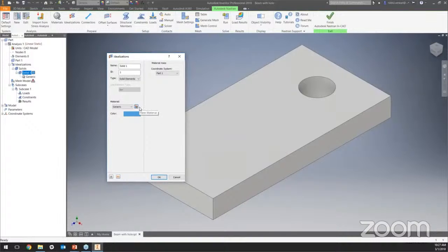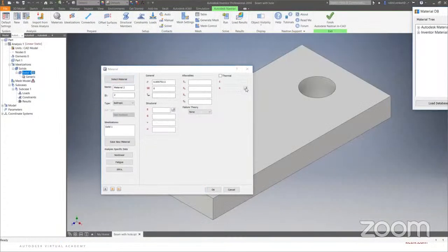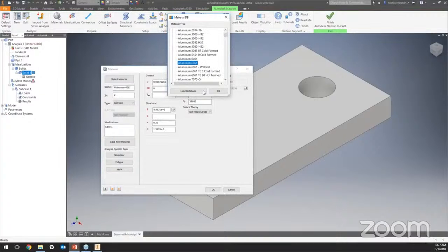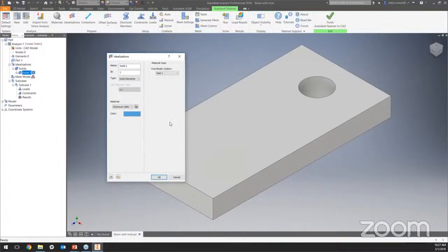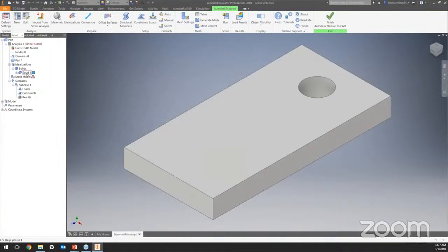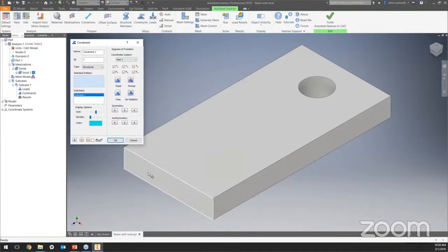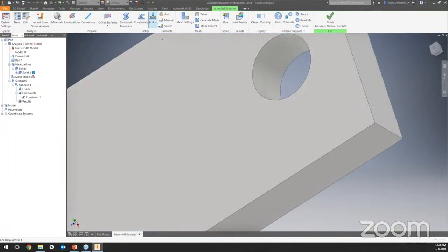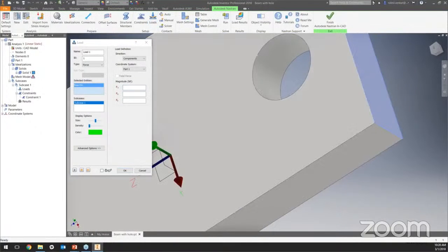Yeah. So for this, I'm just going to choose a material. I will pick 6061 aluminum because Nigel seems to like that. And the color here is just to represent your actual mesh. So this is a really simple problem, just a very simple bending problem. So I want to fix this end, apply a load on this end, let's say minus 5,000. And minus just represents that it's in the negative y direction.